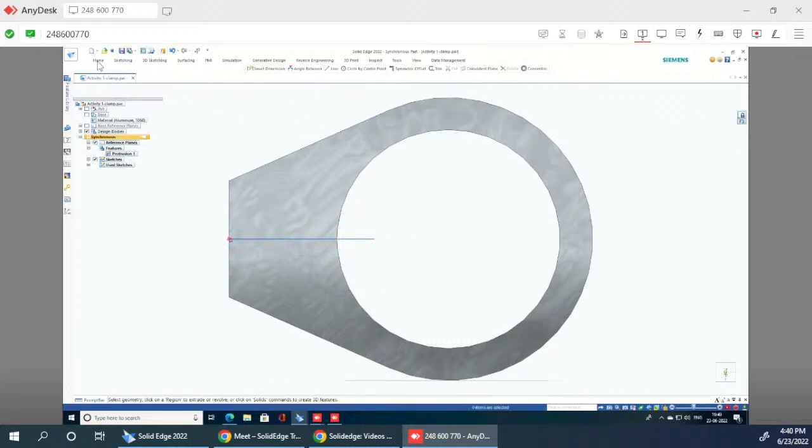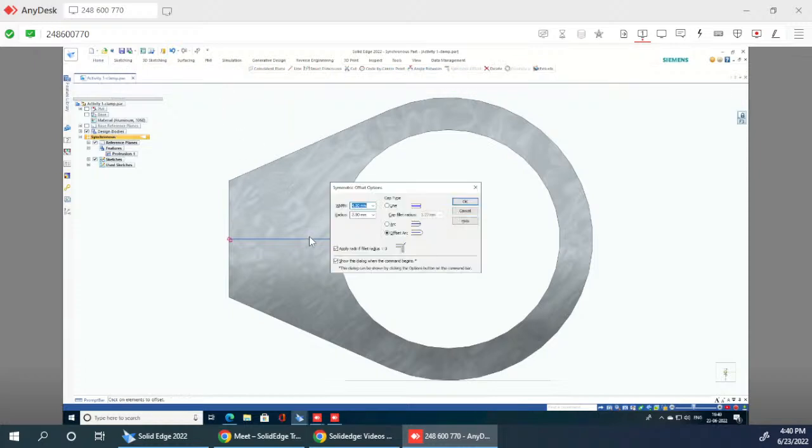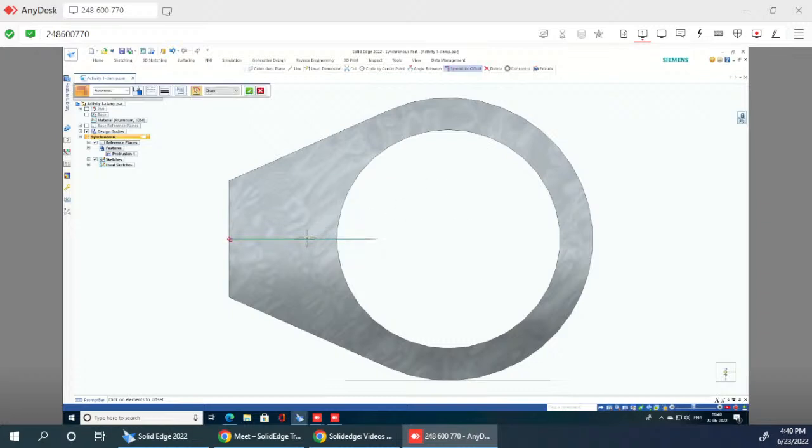And then you have the option here for the slot. Okay, so choose this option, width and all, how much you want. 4 mm width. So click OK and select the side, single, click OK, and there you have it, right?